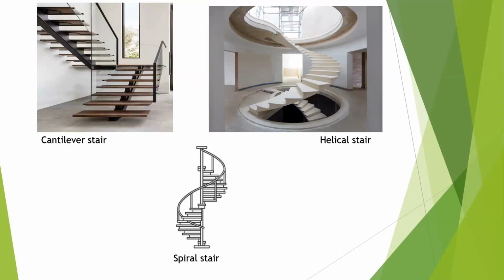I would not advise that this spiral stair is constructed in situ. I would advise that the spiral stair is constructed as precast, because a lot of spiral stairs that are constructed in situ are always rough. This is not to say that you cannot construct your own in situ and it will be neat. However, I would advise that you do a precast if you want a very good job without stress. You understand? So that is that about stairs and the types of stairs.